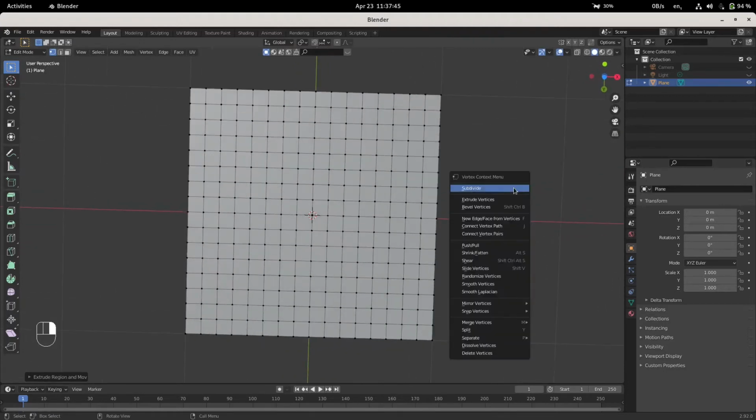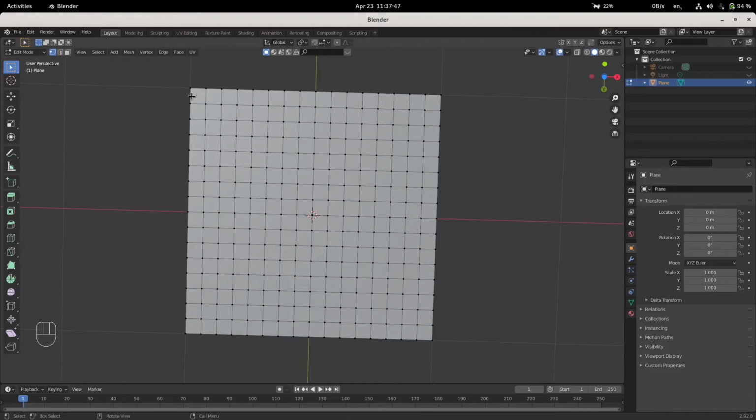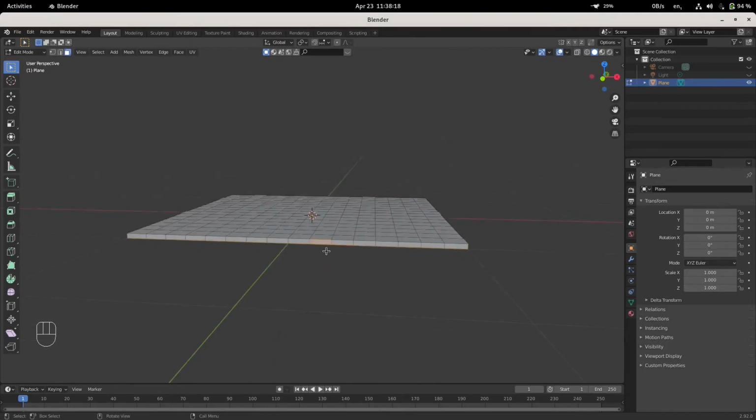Now pressing C button on keyboard we will enable the brush selection mode and try to select side planes. It is on edge selection mode, vertex selection mode. Now we will enable the face selection mode and we will select the side faces of this plane using brush selection tool, which we got using the C key, and we will also select the extra corner face of each side, and we will make sure that no extra faces are selected.